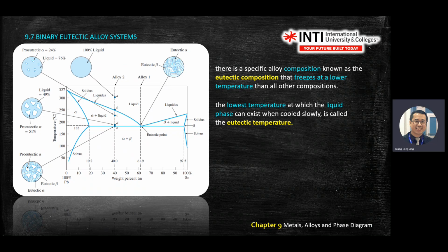Very important, huh? This eutectic temperature, in the exam, we don't tell you what the temperature is. You need to read from the graph. Okay, so again, how to find eutectic? You identify where the liquid phase is. Use your ruler, slowly drop down your ruler.